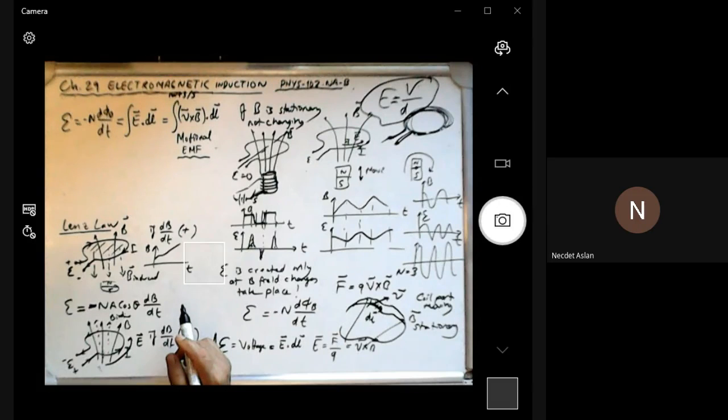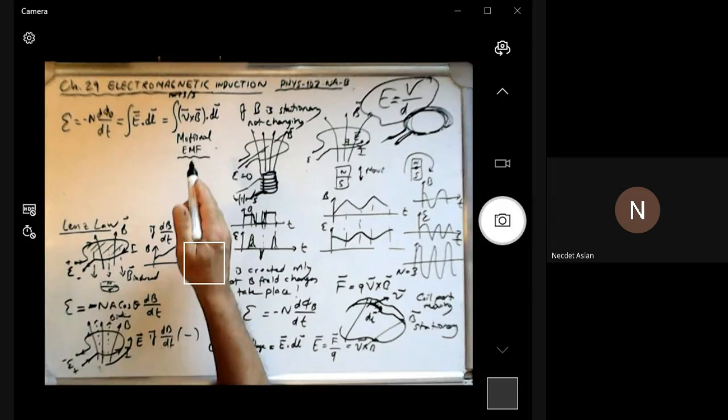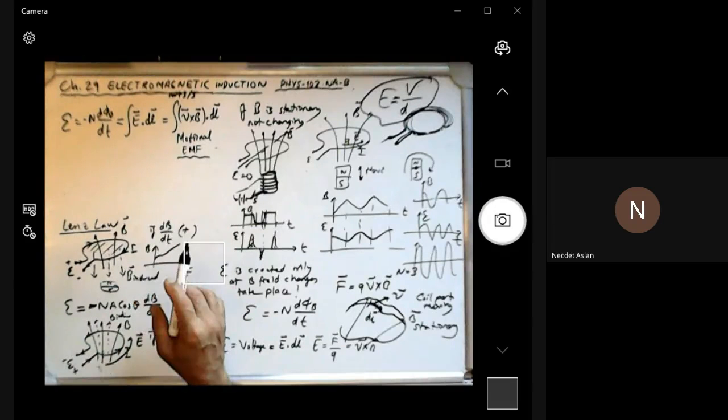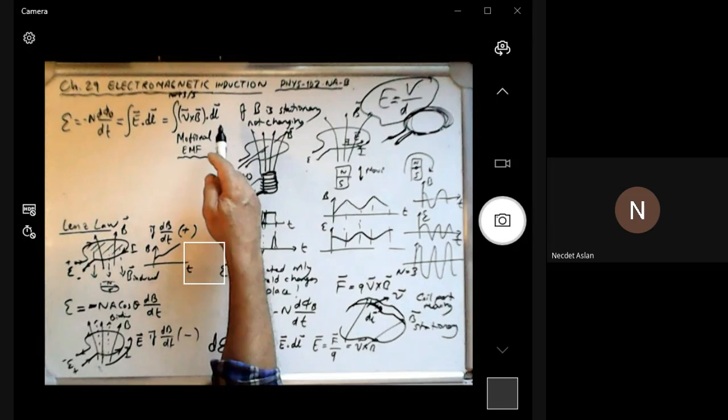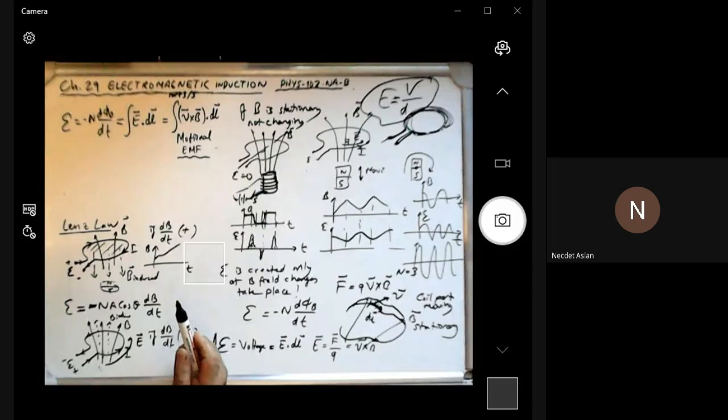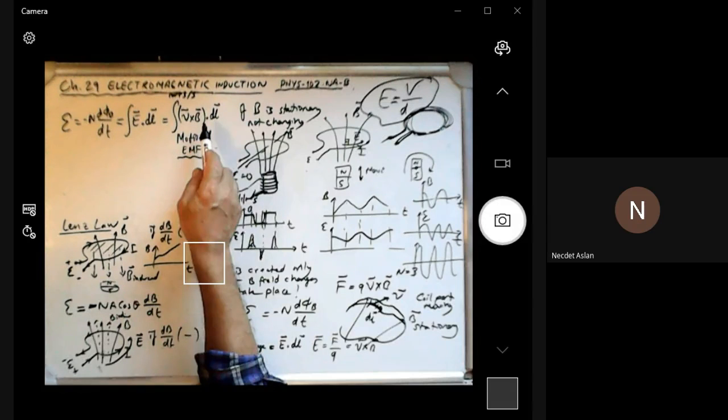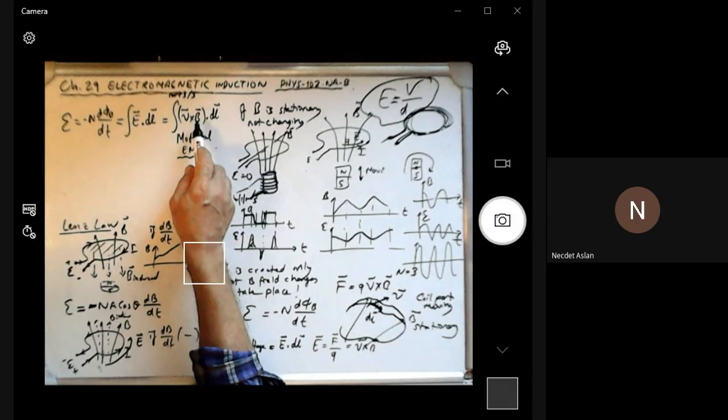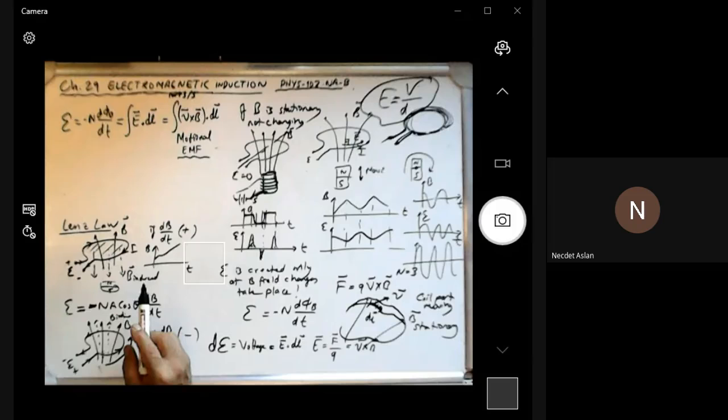It's due to the motional EMF. Your antenna circuit is moving, and there is a magnetic field. Actually, in the lines case, the magnetic field is not constant but changing at 50 hertz, because the line frequency is 50 hertz, and because of this some little electric field is created, and this causes some kind of parasites. So this is the general form of motional EMF.